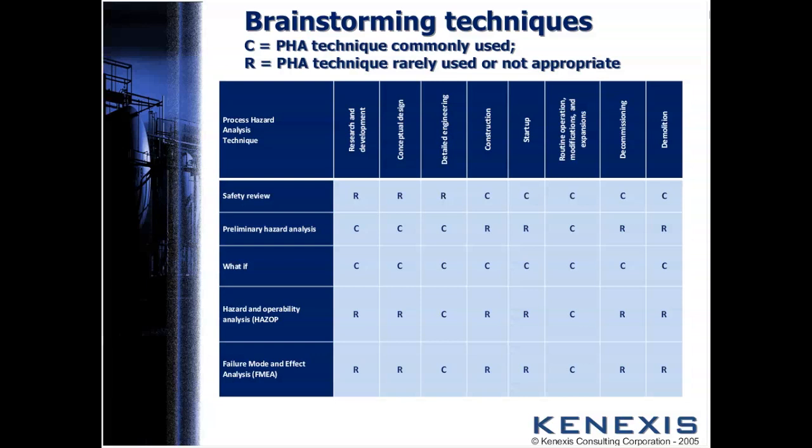But the main reason that we want to look at HAZOP is that it's a great, structured technique for determining the hazards in a process, which we can accumulate and view later to determine whether safety instrumented functions are necessary. It works on continuous and batch processes. Now, the HAZOP analysis technique does require up-to-date P&IDs and operating procedures and things of that nature. And it does require considerable knowledge of the process, the instrumentation, and the operation. So you've got to have a number of experts that know the process well in a HAZOP.